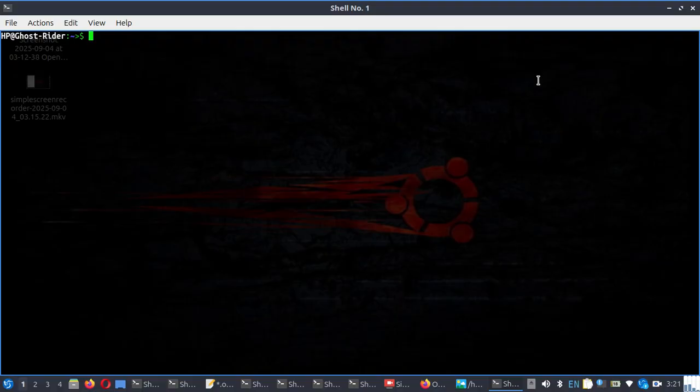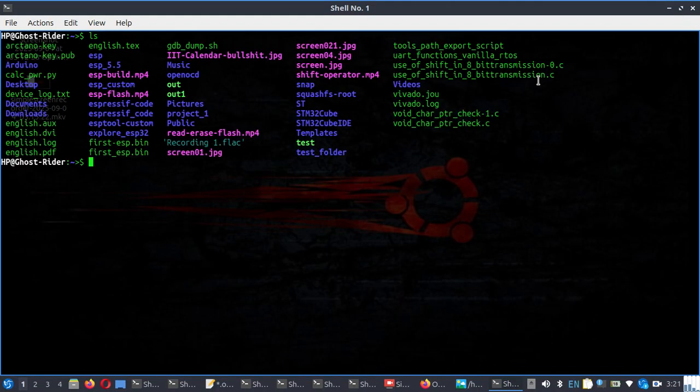Okay, let's open a new session. For doing this, you'll have to first locate the OpenOCD in your system. In my system, I have multiple OpenOCD installations. I have a standalone OpenOCD also, but it is more complex compared to the bundled OpenOCD that you get with an ESP32 toolchain. So in this session, we are going to use the OpenOCD which comes bundled with the ESP toolchain itself.